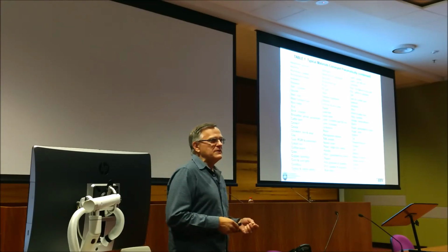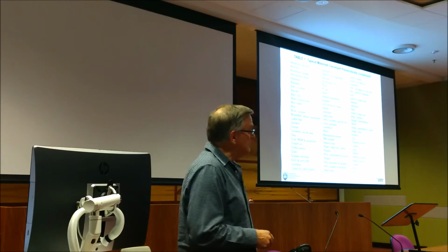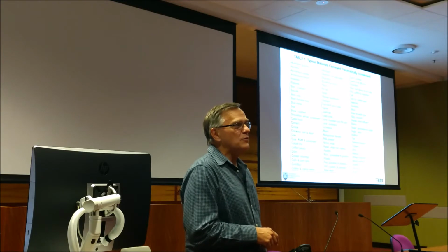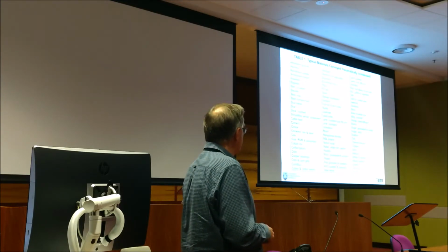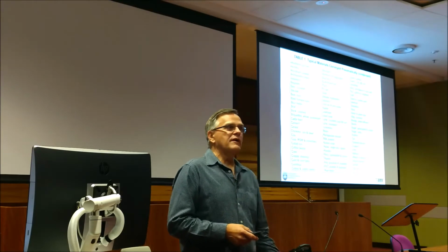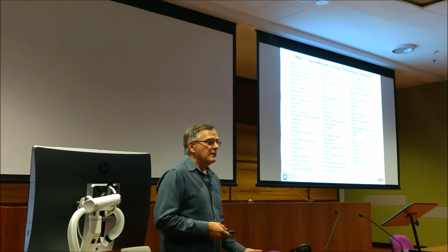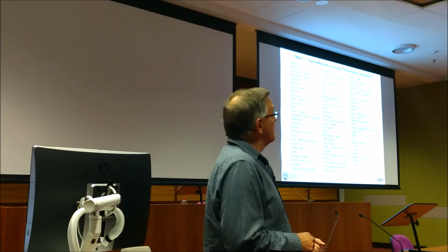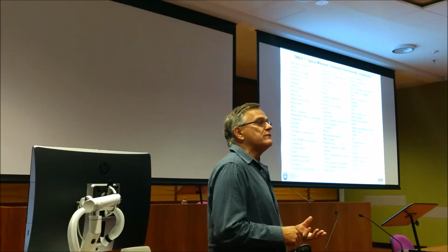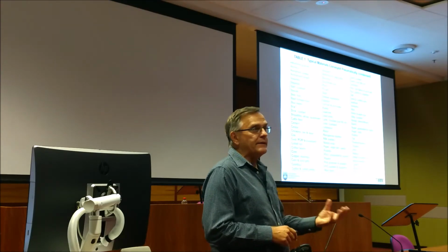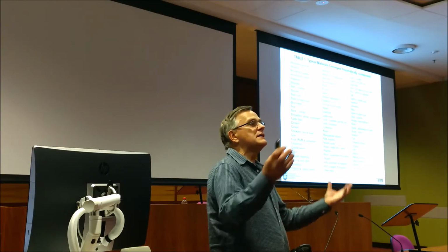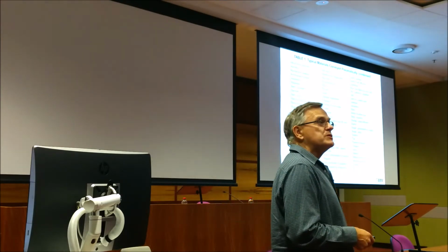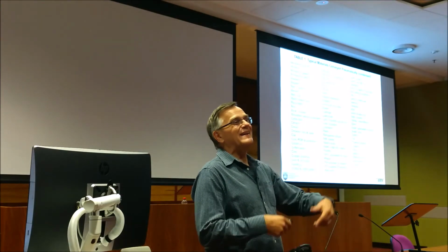Okay, so I mentioned briefly before about different products we can convey pneumatically. So here we see a condensed list of all the products we've conveyed in Wollongong, and it's by no means complete, that list. And these different products are conveyed pneumatically for all sorts of different reasons. For example, your product may be toxic. And one advantage of pneumatic conveying is it's an enclosed form of transport. We're putting our powder through a pipeline so it doesn't escape to the atmosphere. So in some cases like zinc fume, it may be a waste material, it's highly toxic. You don't want that to get out into the atmosphere.